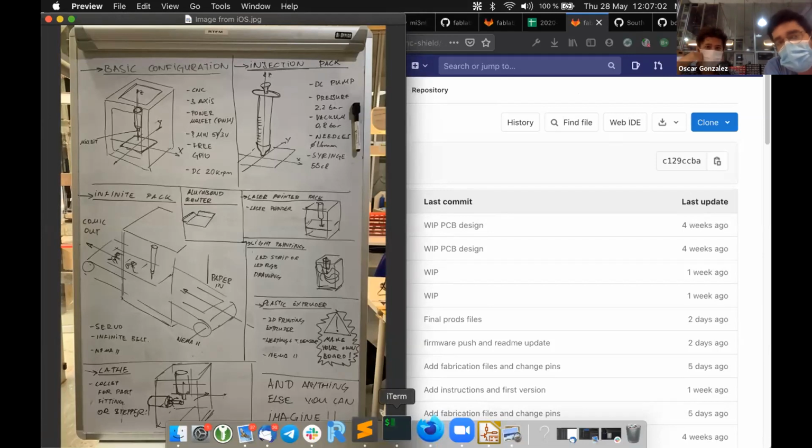The bad point is, yes, you are calling an address to a motor and you are stating that it needs to move, but there is no one managing the general movement. Each board manages its own personal movement, but there is nobody controlling the coordination between different axes.